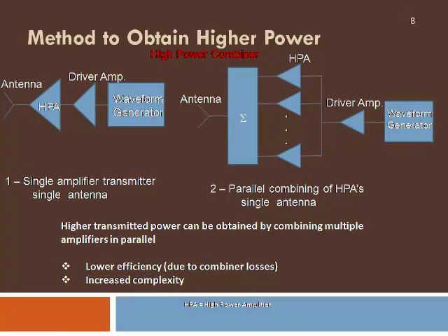Here, adding the power outputs from the different power amplifiers is a difficult task, but a single antenna can definitely radiate all this high power very effectively. So there are plus and minus points of using several amplifiers together, or individually with different antennas.